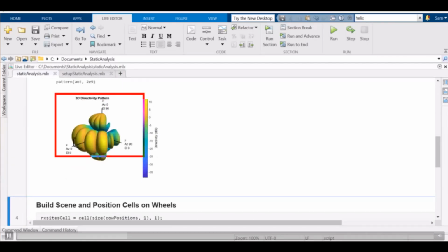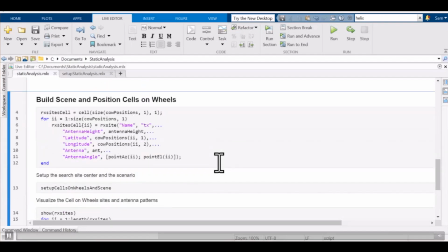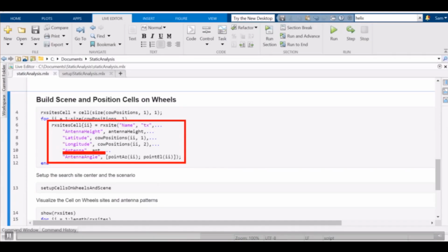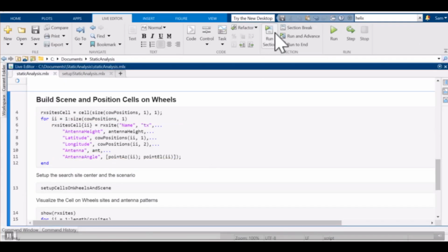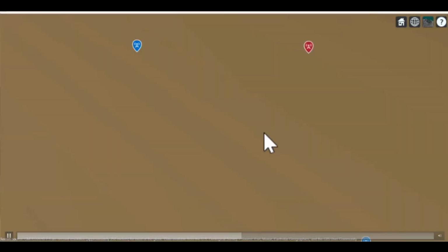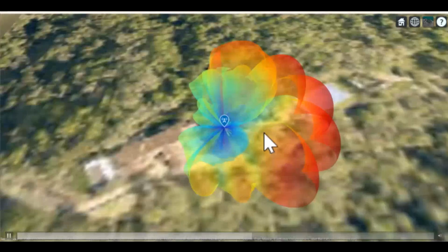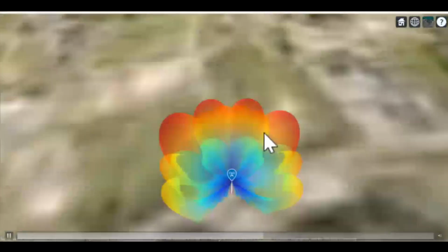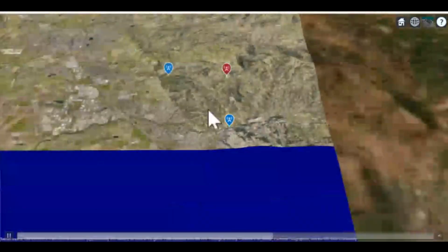So when the drone is in a yellow area, you can see that the signal is transmitted, okay, and received by our ground station with a power of minus 60 dBm, okay, which is well above our threshold to close the link. So you can see details about this coverage.